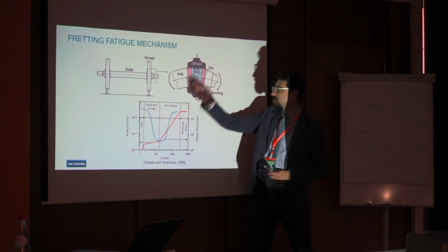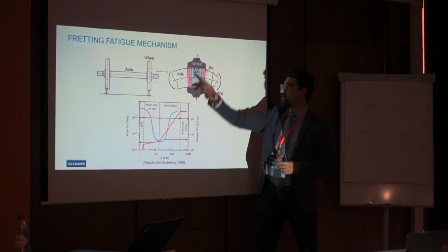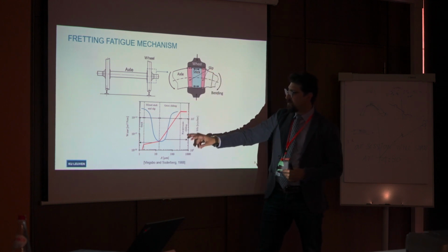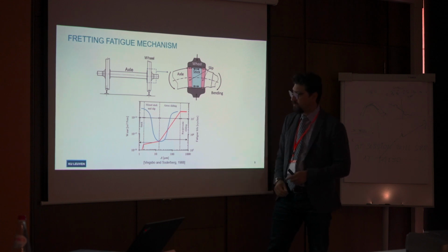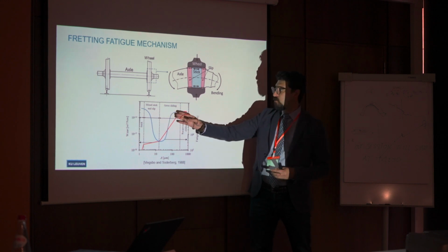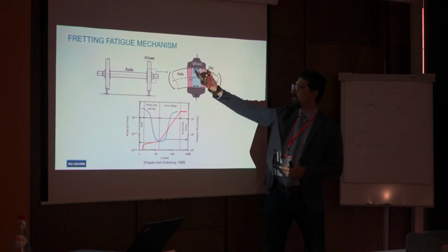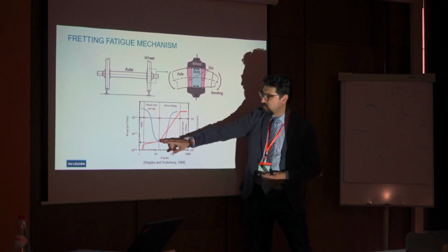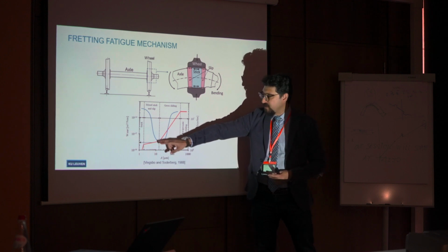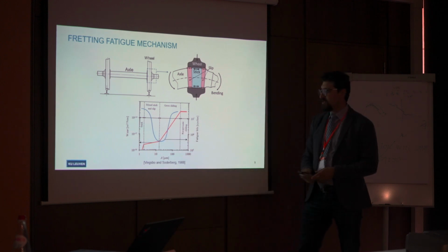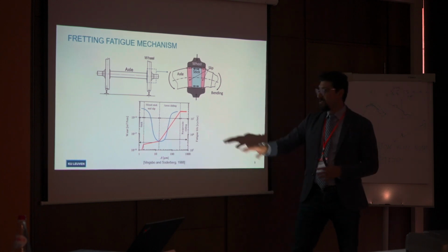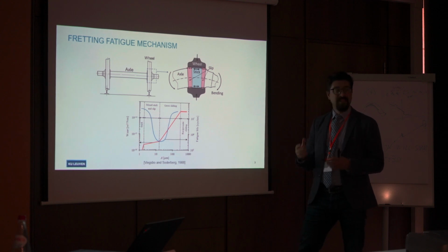Here you have sticking, so there is no relative displacement. Here we have a mixed slip and stick, so it's sticking and slipping, and here we have gross sliding, a fully sliding condition. What is very critical here is the border between the mixed slip-stick and the gross sliding. When we are at this situation, the fatigue life is minimum. We have some limited, local wear process, but finding the exact point here is very challenging because the amplitude we are talking about is around 10 micrometers, in global measurement.